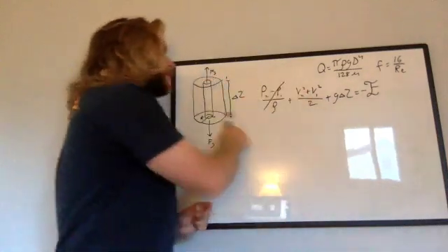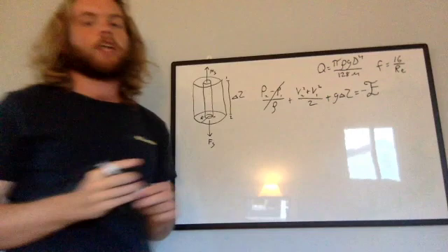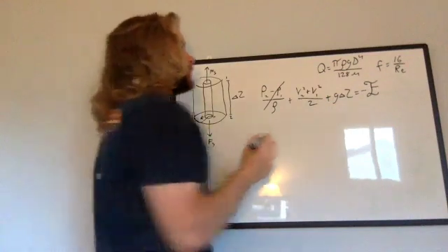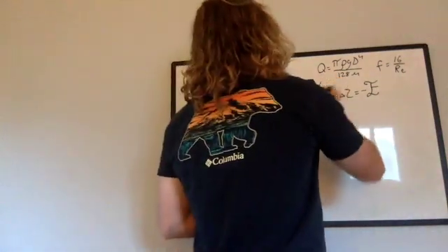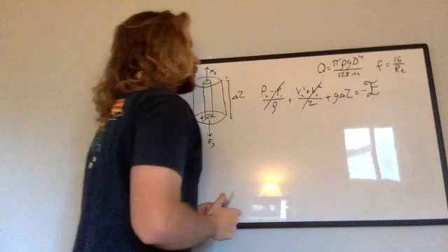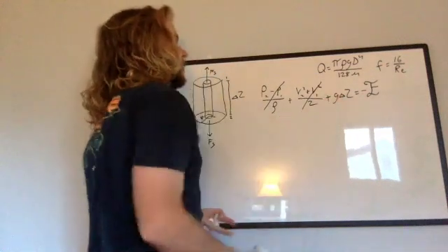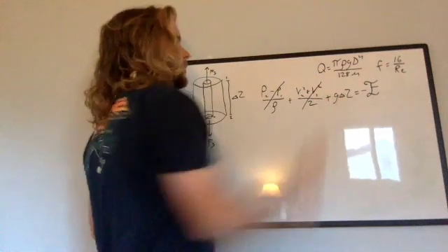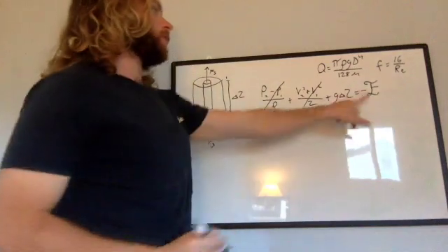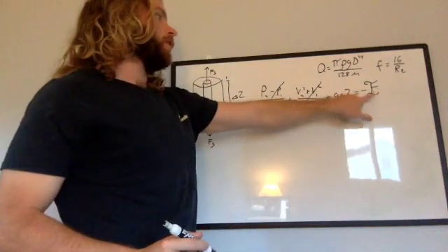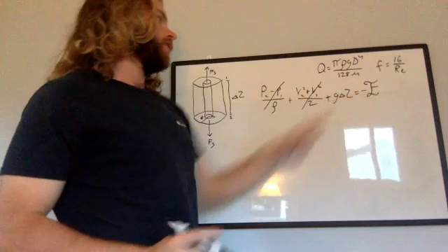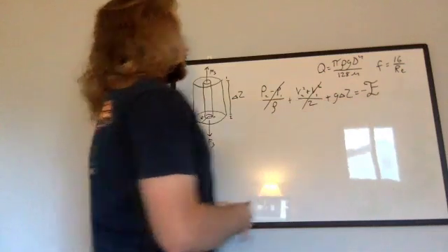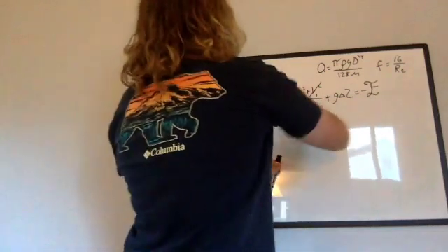And we know that the velocity of the fluid within the pipe is not going to be changing either. That's going to remain constant, so we can cancel this out. We are just left with our acceleration due to gravity multiplied by the change in altitude being equal to the negative frictional heating right here. This is our expression for the frictional heating. So we can just erase all this over here.